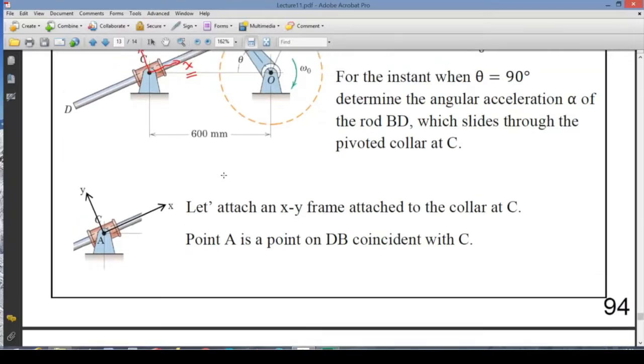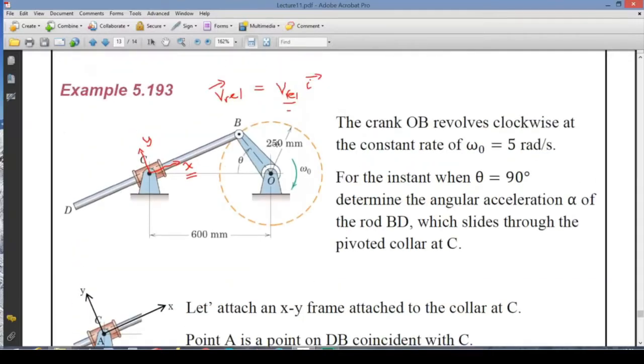We can start out by writing our equation, and remember that when we are writing out this relative motion based on the rotating frame, we have terms like the Coriolis acceleration, omega cross product V relative. Also, we have the centripetal part as omega cross product omega cross product R, whatever the R is there.